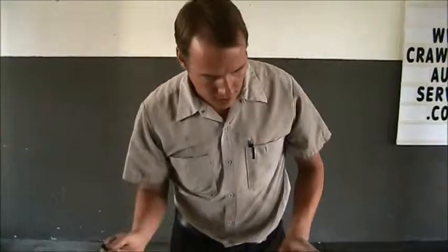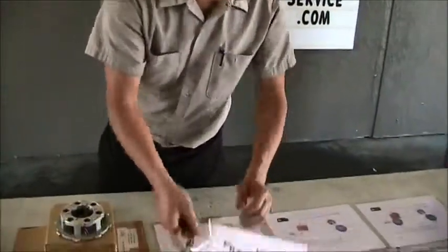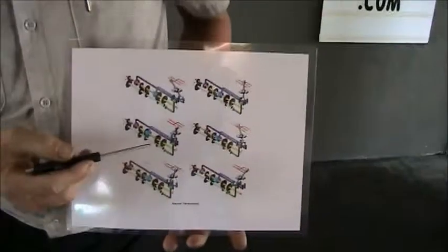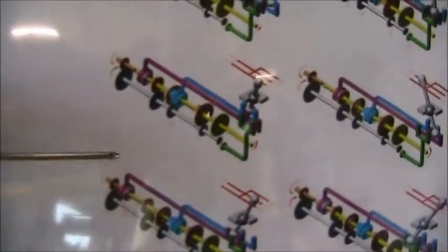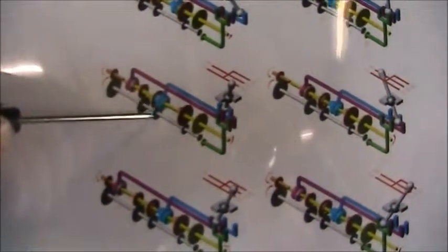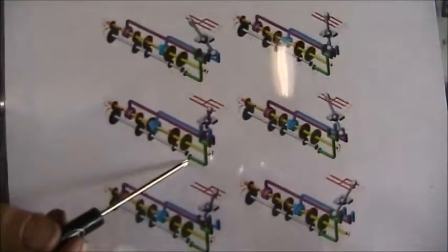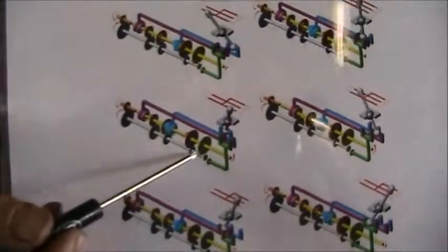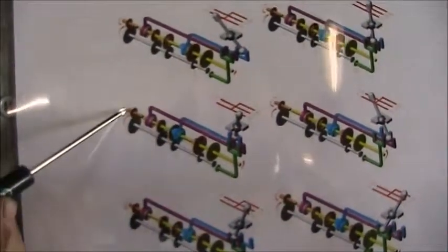Now, I didn't go through that in a manual transmission, but every time you add a gear, the rotation of the next gear is going to be reversed. So to achieve the same direction of rotation input to output, the power has to come in here, down here, over here, up here, and then out. That's how the transmission works. These bottom gears are mounted rigidly to a shaft. These gears are not mounted to a shaft. You select which gear attaches to the shaft, which gives you your gear ratio and allows the vehicle to go.